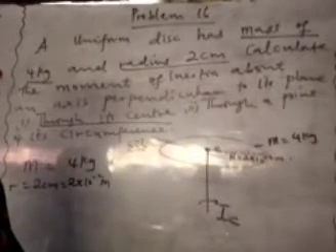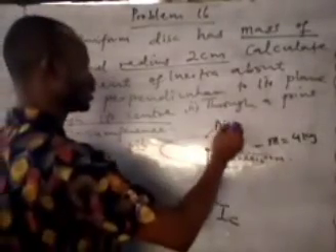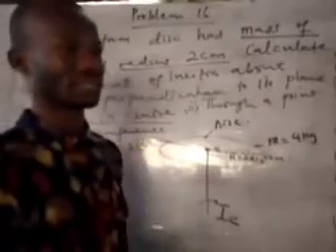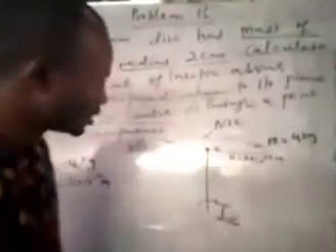So everything is good to go. Let's now see how we can solve this. Now remember, we have given the formula for a disk. This object is a disk. When you want to find the moment of inertia of a disk about an axis through the center of gravity, it has a formula. Who can remind us of the formula? Very simple. The formula we gave was that the inertia I through the center of gravity equals half m r squared.